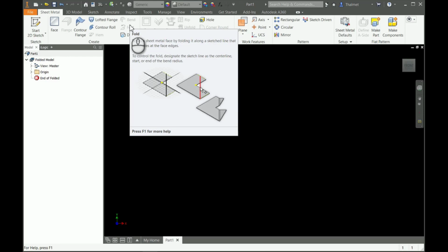Now, this is by design because we want to think of sheet metal a bit differently than if we were just machining up a part itself. And something else that we have to take into consideration whenever we are creating a sheet metal part is the material itself. Sheet metal is usually 0.25 inches and smaller, so it's very thin material, which means that we have to be mindful of how we bend and break the piece in order to get our finished product.